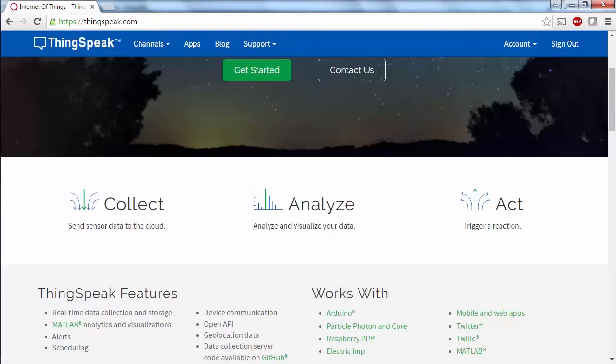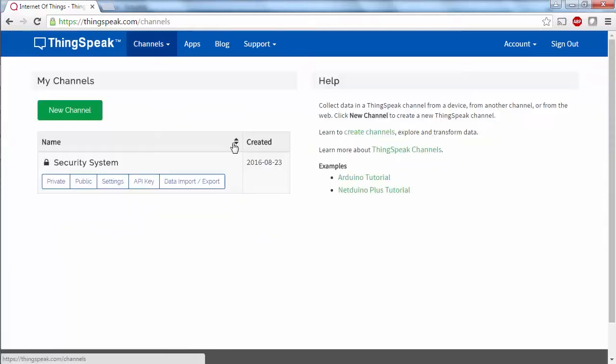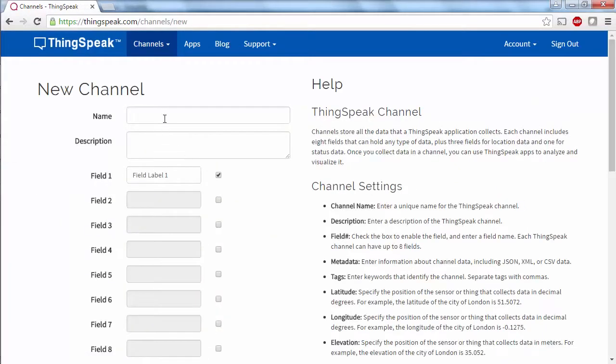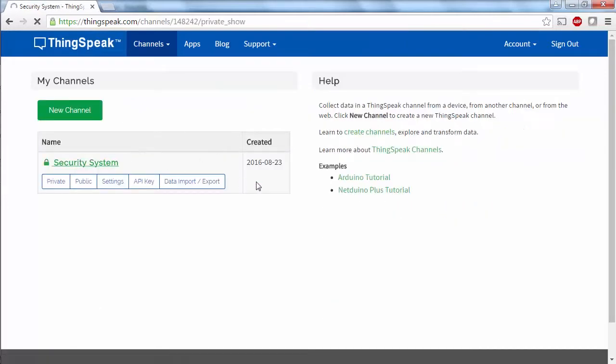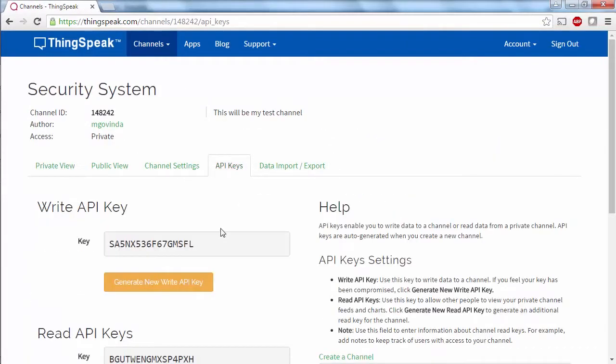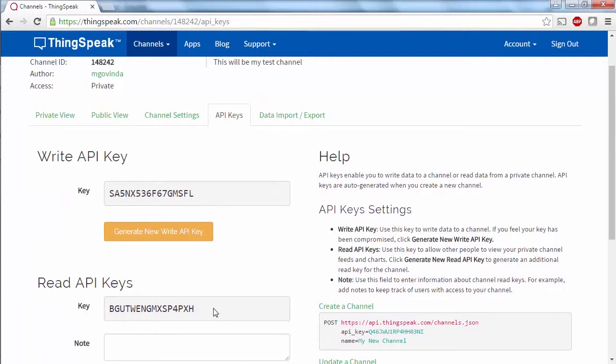We will now see how the ACT portion of ThingSpeak helped me in the context of this demo. So you can create a new channel and fill out all the necessary details about the channel: title, description, and field. Instead of creating a new channel now, let's go take a look at the one that I've already created. To get the right API key that I showed in the Simulink model, you will have to go to this section under your channel.